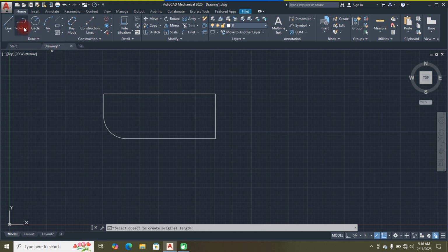Another thing I may do, so that I do dimensioning of all possible techniques, let me have an inclined line. So I pick the line command, then I select the midpoint. As you can see, it is a midpoint, and I find the midpoint of this other line like that. I press enter.